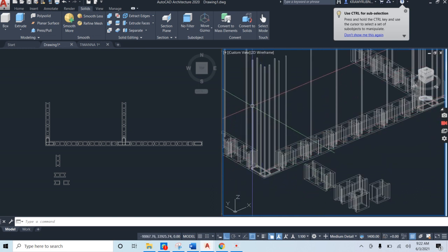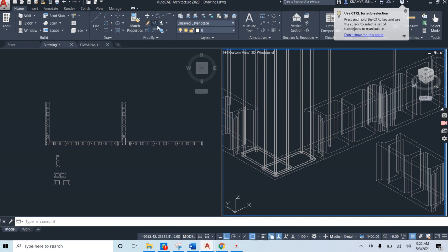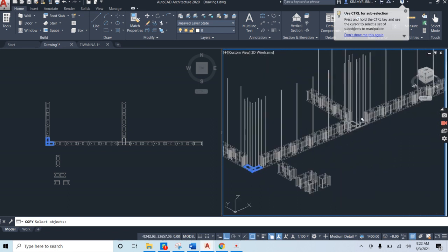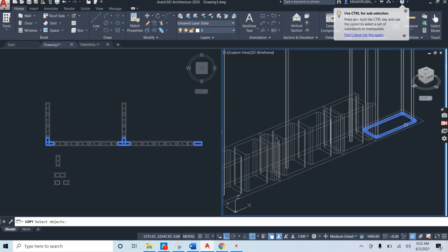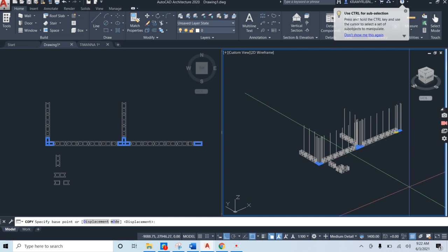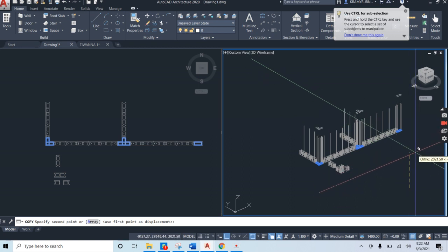Finally, along our stiffeners, our steel bars are going to be distributed at approximately 10 inches in a vertical way. Let us go ahead and copy both stirrups for our L, both stirrups for our T, and our single stirrup for our I. Enter. Click on screen, and like I said, with your ortho on, we're going to be distributing these stirrups 250 millimeters apart. So let's go first, 250, enter, a copy is made.